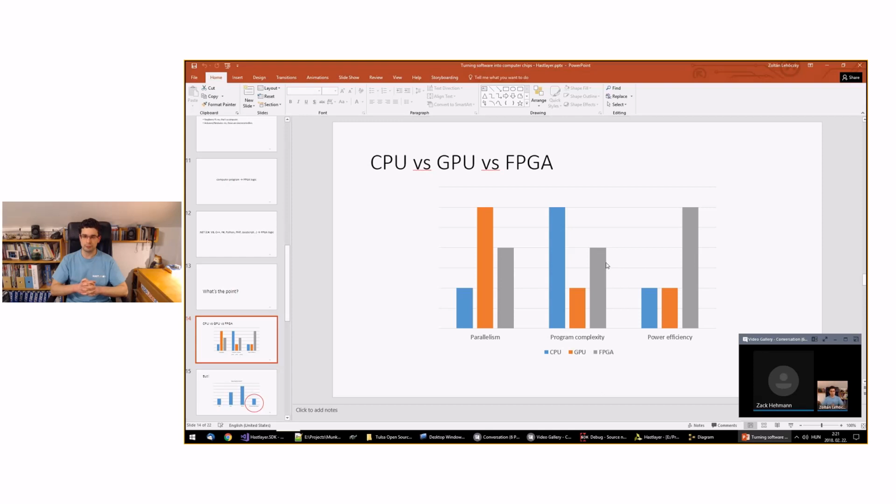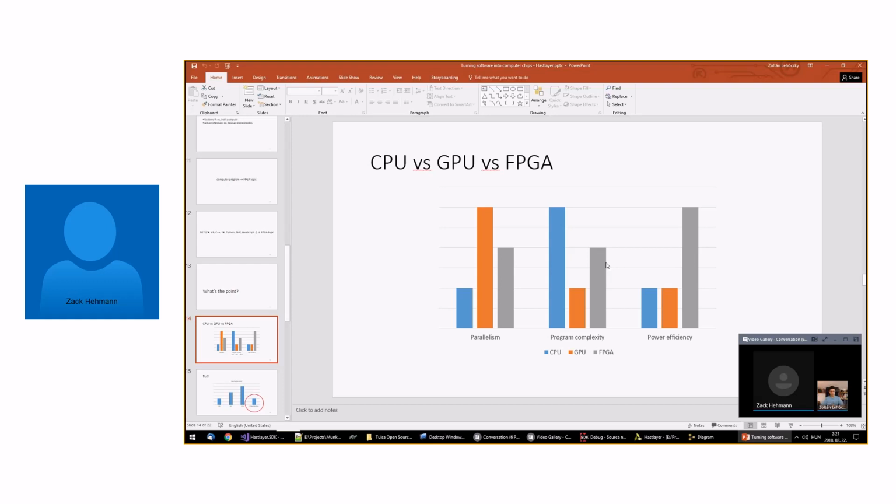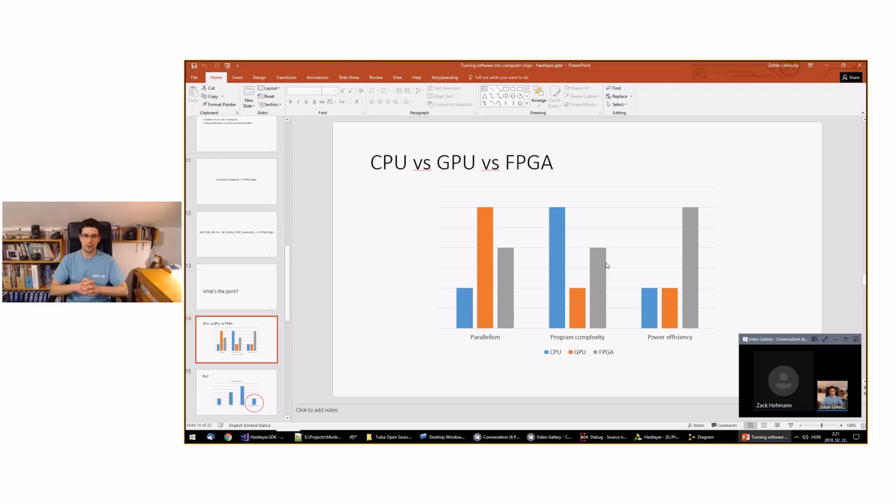Do certain companies use FPGAs to basically do a proof of concept for an ASIC? That's actually one of the foremost usages of FPGAs. And originally, if I'm not mistaken, FPGAs were created precisely for that task. Now they are much more, but originally that was the case. So, for example, a chip manufacturer like Intel has enormous FPGAs, and a cluster of enormous FPGAs, to emulate, for example, a recent CPU.